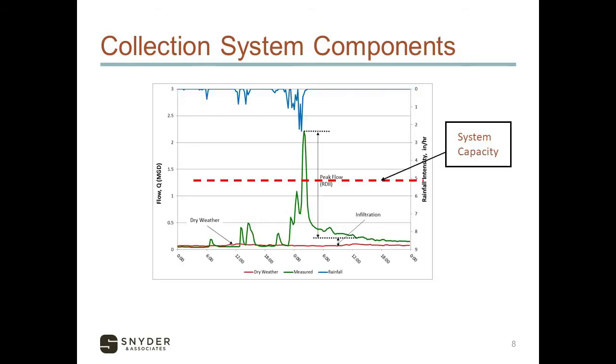This graphic here is a hydrograph from a flow monitoring output. We're typically using graphical output to understand the data that is collected, and we will plot rainfall intensity at the top, which is shown in blue. We like to do intensity in inches per hour versus if you have a rainfall that occurs over an entire day, maybe you get 3 inches, but did 2 of that occur within an hour? The peak response is going to be a lot more important to understand in that fashion for us to see how quick the system responds and how we can quantify the inflow and infiltration.